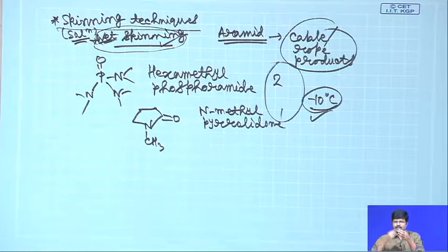Those fibers are in the solid state and they have a long range, strong orientation along the length of the fibers, that is what you have to achieve. So, what you start with is a highly concentrated solution of this para-aramid that you have prepared. Ultimately, after the reaction, you will get pellets of this material, and then you pulverize this material and then you dissolve it in a suitable solvent.